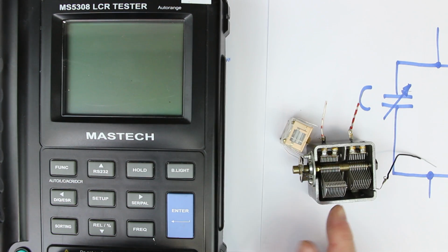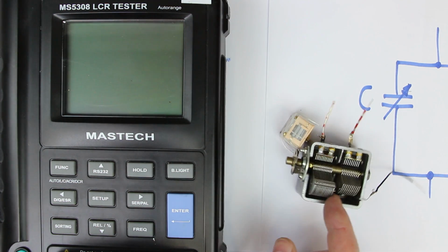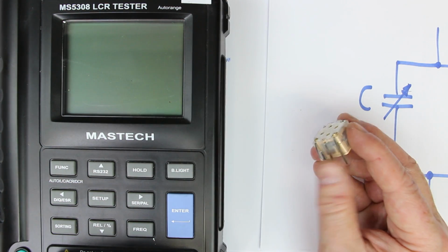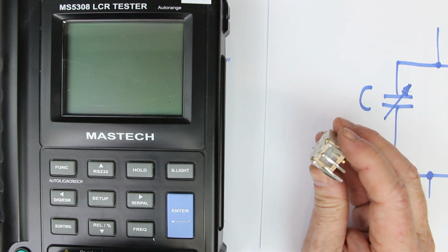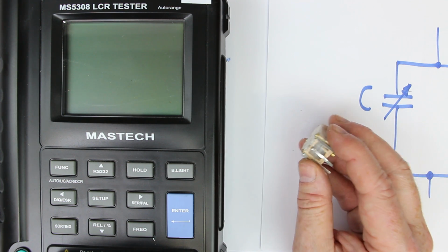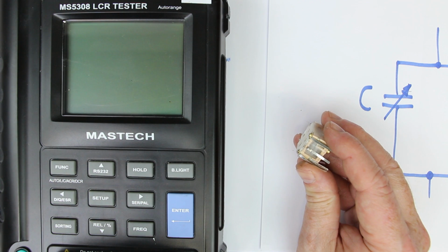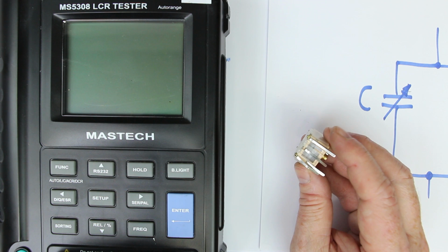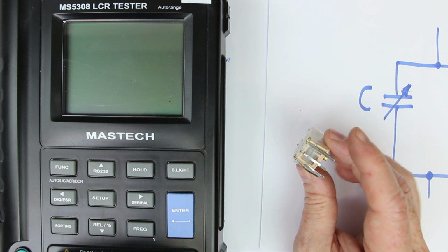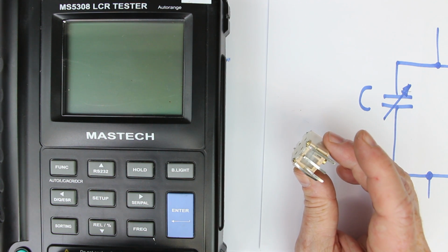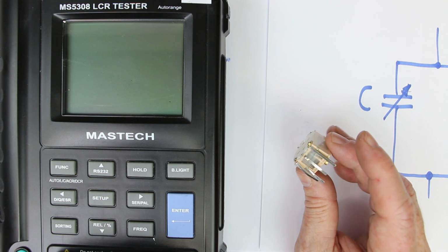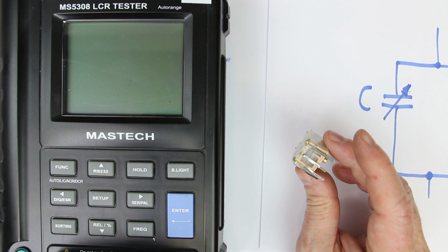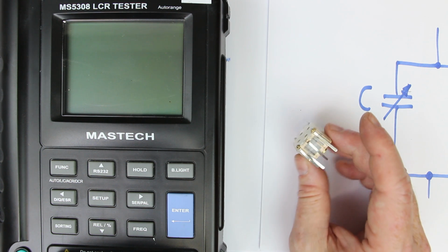Here we have air as the separating dielectric material, and air has a dielectric constant of 1, like vacuum. And of course, if we take the plastics that are also used in plastic or film capacitors, then we achieve the same capacity with fewer plates, because the dielectric in between the plates has a higher dielectric constant.